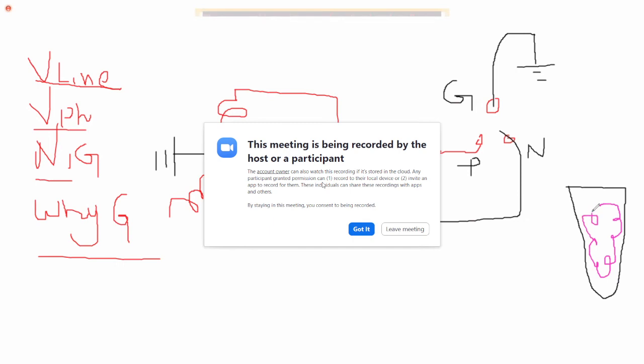ये इसके 2 पॉइंट हैं हीटिंग एलिमेंट के। अब मुझे ये बताओ, जो हीटिंग एलिमेंट के 2 पॉइंट हैं, which 2 wires will be going to this one out of P and G? Phase or neutral? Phase and neutral, very good. And generally it is 220 volt. So is it true that phase neutral is 220? Yes, sir. ठीक है, तो इसको मैं लगा देता हूँ। न्यूट्रल को मैं एक जगह लगा देता हूँ।